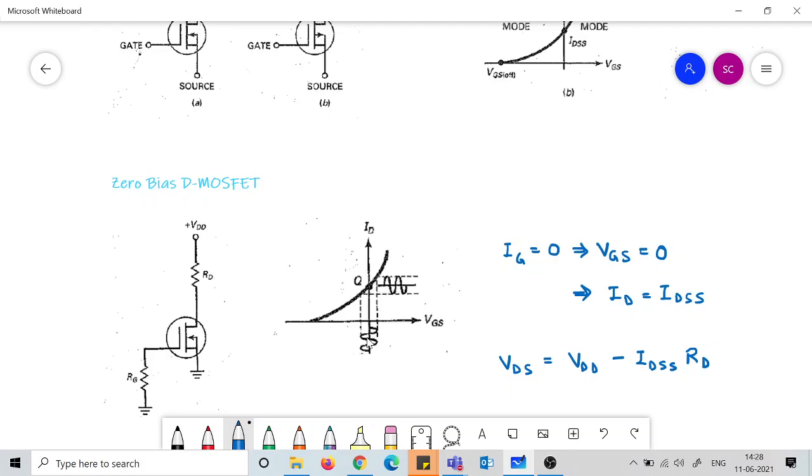So if you supply some AC signal at VGS equals to 0, then this AC signal comes out as an AC current ID with some degree of enhancement, which is given by the transconductance gm. The same transconductance gm idea is still there. So gm times VGS will be ID, and you can have this relationship still valid at VGS equals to 0, which was not possible for JFETs.